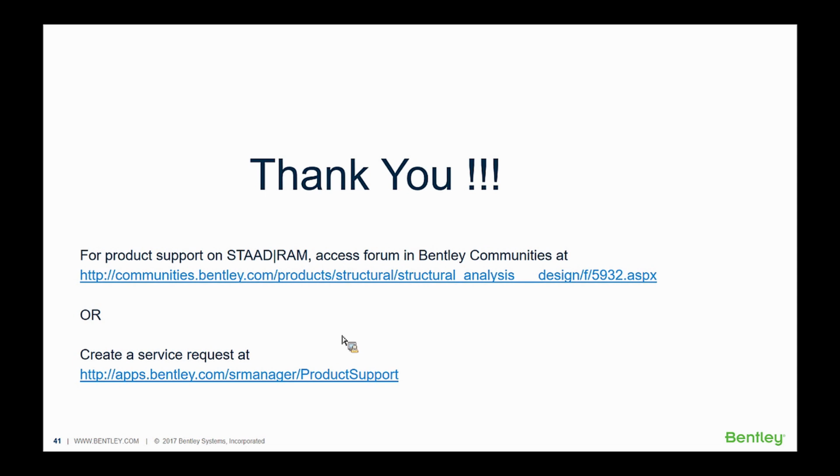Next question is, why in response spectrum analysis you don't have load combination of accidental torsion and seismic load? In the response spectrum analysis, you may remember that when I specified the load definition itself, it involved checking a dialog box called use torsion, and that had the accidental torsion option in it. So as part of the definition itself, the accidental torsion has been included. So that's why I did not need to create a separate load case for the accidental torsion.